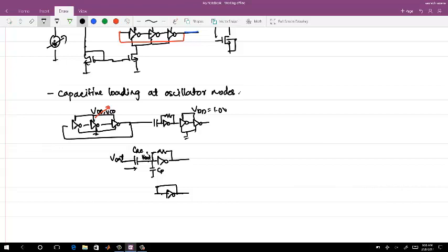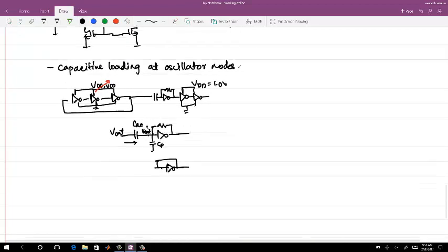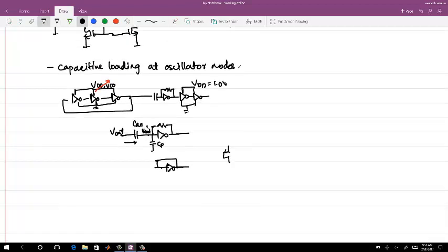Okay. So a way to do away with that is, in place of using a single inverter with gate and drain shorted, to use a ladder of switches, with the same VDD and ground, and I size this accordingly so that it is always biased at its midpoint.